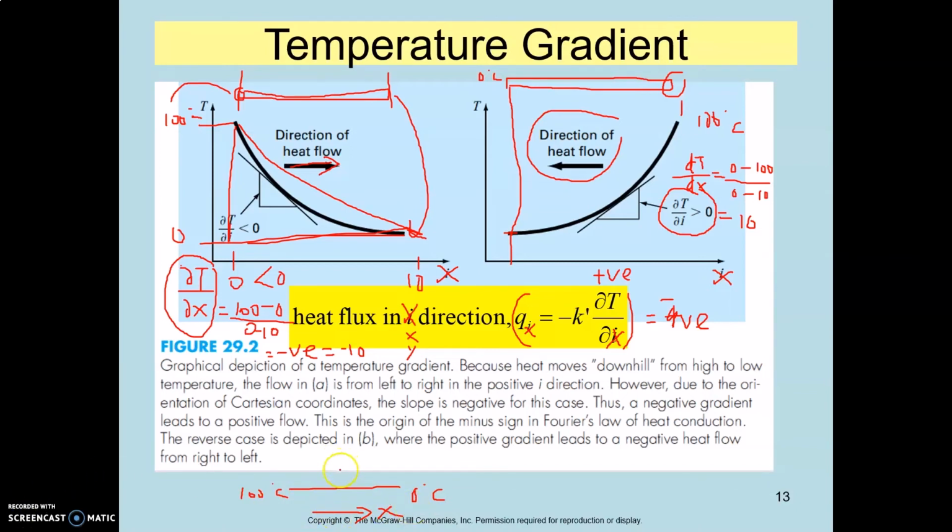Where is the direction for the heat flux? Of course, based on the high temperature, we expect the heat to flow from this point at 100 degrees Celsius to 0 degrees Celsius. So this is the direction for our heat flux, Qx. In other words, when you compute this, you should get a positive value, meaning it is in the same direction as the x direction.